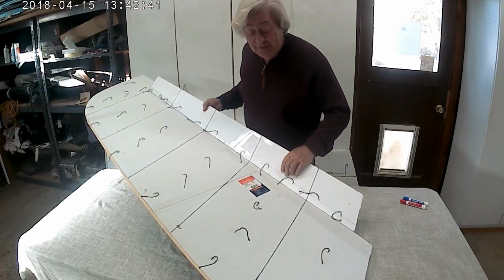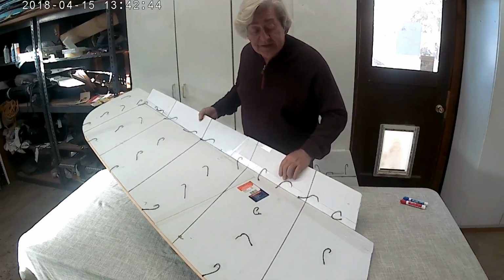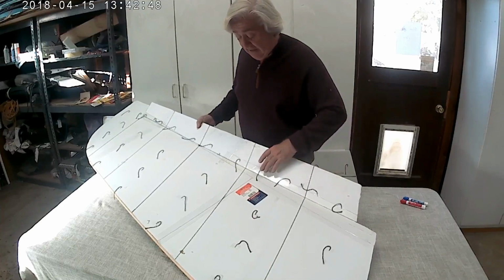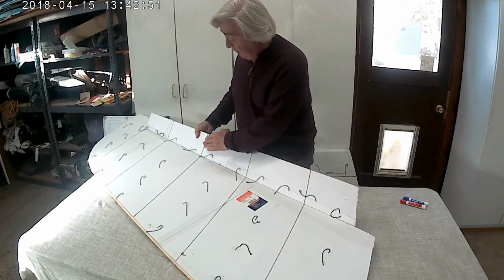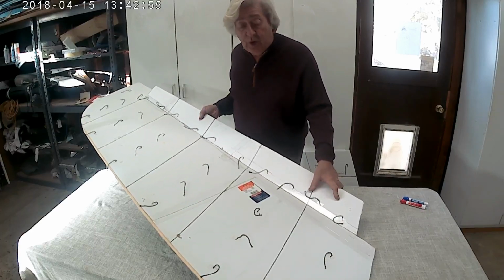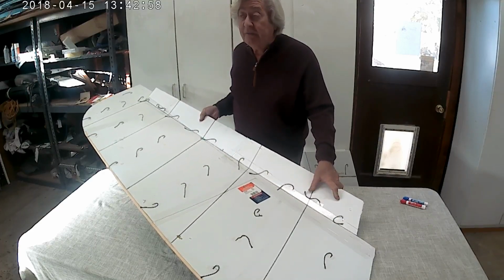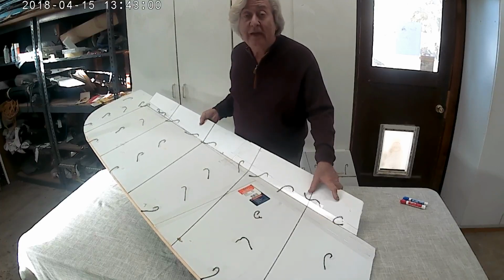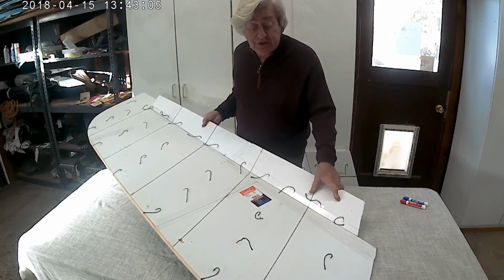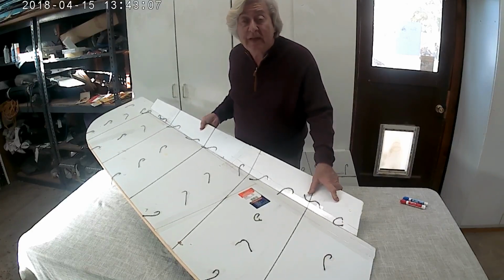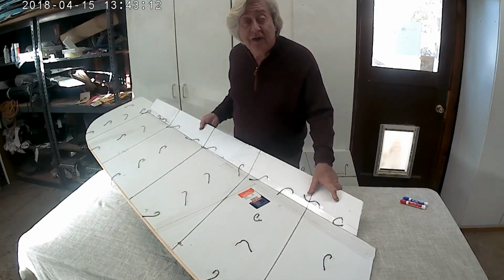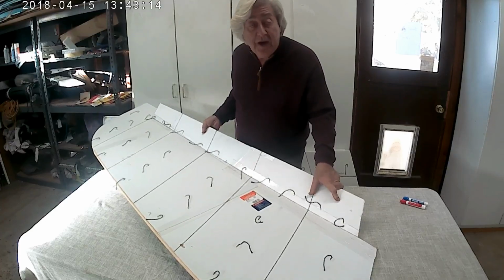And I'm going to run you a little bit of video here that shows you this under test, and you'll see these tufts. When this comes up like this, you'll see these tufts go out span-wise. And for gliders, this is a really big problem because gliders fly slow a lot of the time and in a turn called thermaling. Sometimes we do some ridge turns really slow also. And quite often in that maneuvering, to adjust our speed, we have to move the elevons a little bit. And sometimes we move them up.